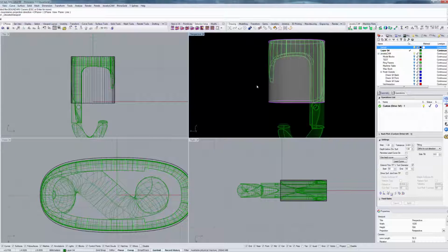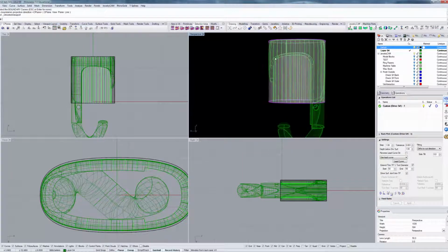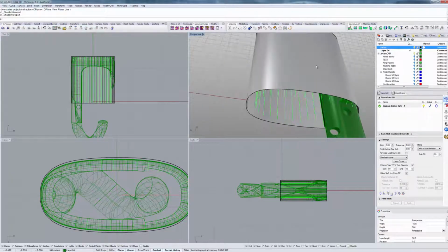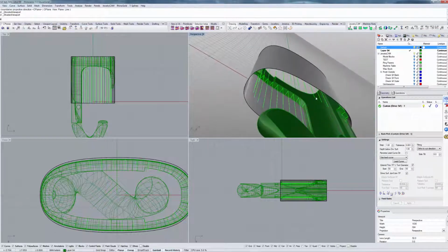If you truly need to do this, it would probably be best to go in with a curve and cut command and cut it out much quicker by really a 2D, 3D operation afterwards. However, if you must, you could specify that you don't want it trimmed and mill it out, and then you will see that it cuts out this whole area underneath. Still, you might wonder why the lines don't fall right through. They're only going so deep.